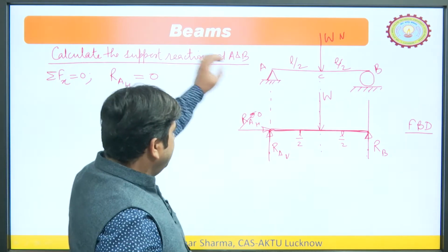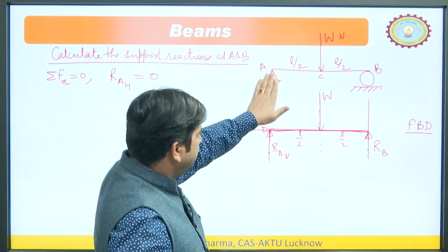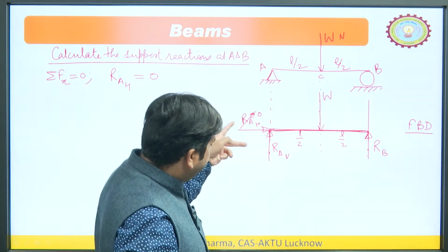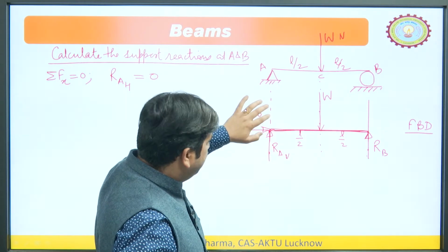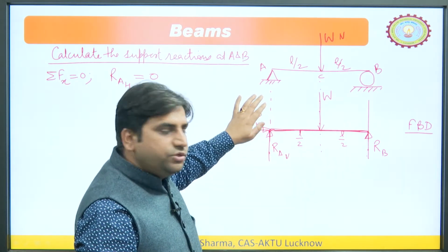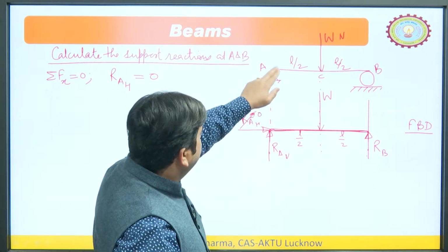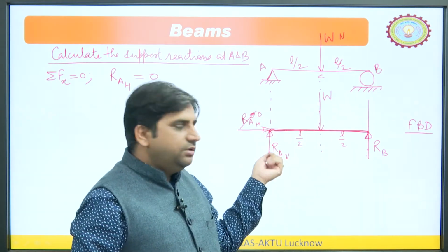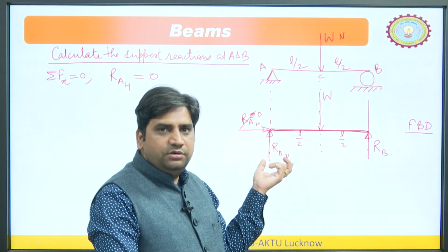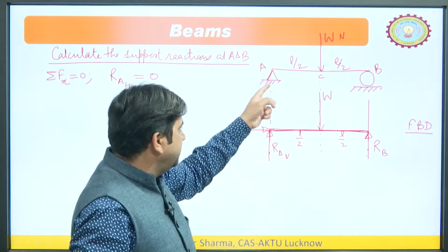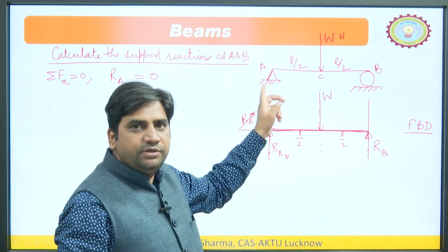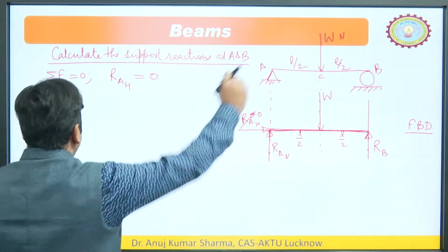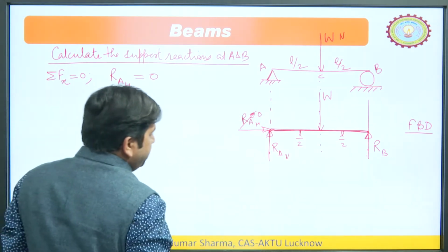If you have taken this support as a roller support, or as a pin joint, you will have to show two reactions, but out of these two, the horizontal reaction is 0. So, if you had taken this support as a simply supported support, the answers you get are also correct. You can take this support as a simple support, as well as a pin support. So, nothing is going to change in the numerical. And before that, you can also take the sign convention.